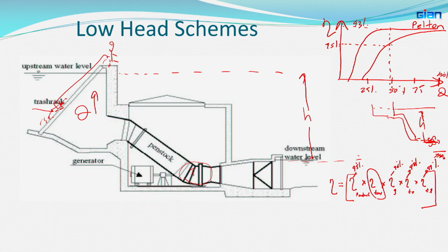If you take a Kaplan turbine, it might be in between, right. If you take some other turbines, there are turbines called pumps used as generators, they will be much worse, right. Therefore, when you use efficiency for power calculation, as per our equation, for turbine efficiency you can't put a constant value.